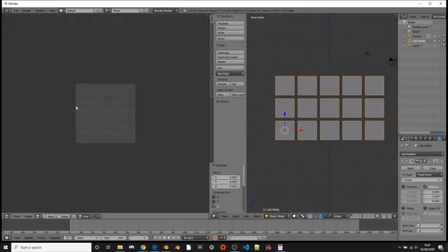Okay, so this is our default texture size, our texture area, and it's given to us in squares because more commonly in games people use squares because they want to optimize content, and it's not necessarily the way that we would work in the live show event. There are times where it is very sensible to optimize content, and I'm going to bring in some models that I've used on other shows in some of the sessions and have a look at that. So the first thing we want to do now is change this texture size to something that's more useful to us.